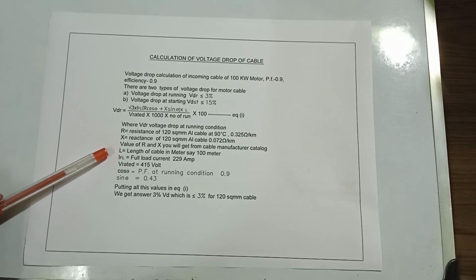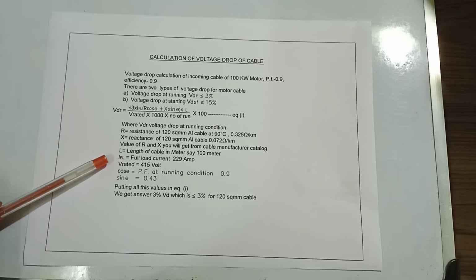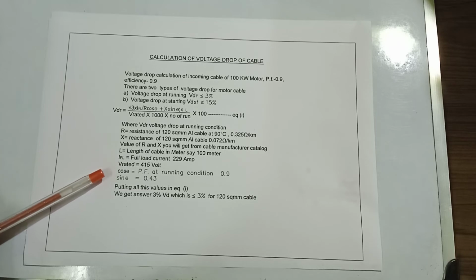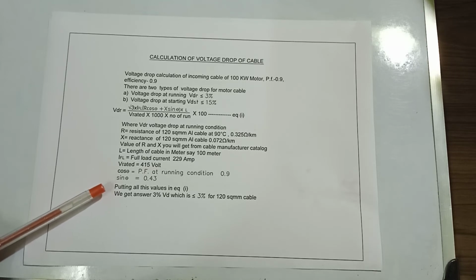L is the length of cable in meters, say 100 meter. IFL is full load current, 229 ampere. V rated is 415 volt. Cos theta, power factor at running condition, is 0.9 and sin theta is 0.43. Putting all these values in equation 1, we get the answer 3% VDR,